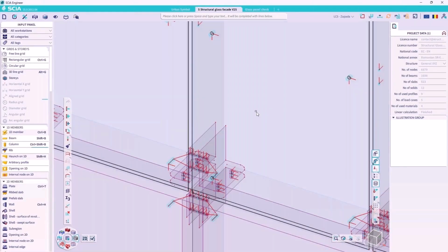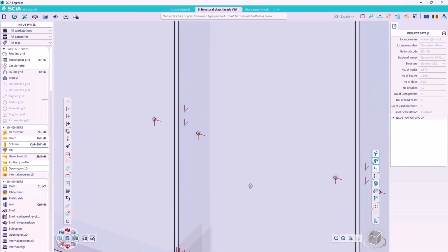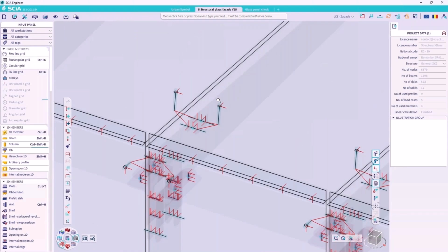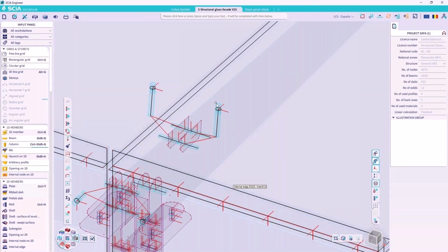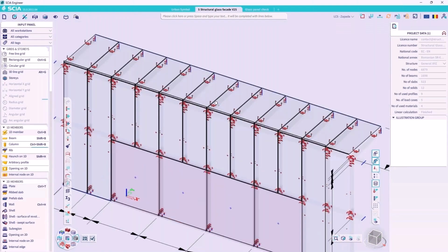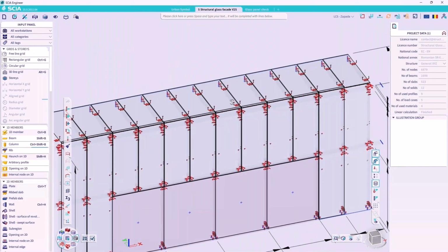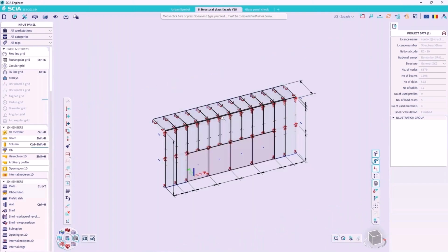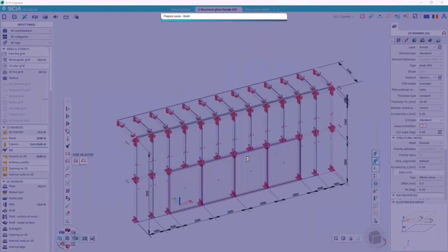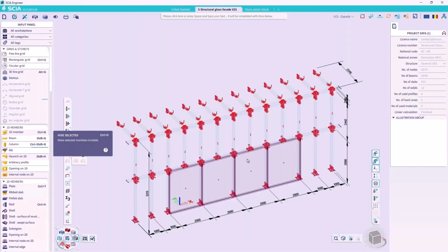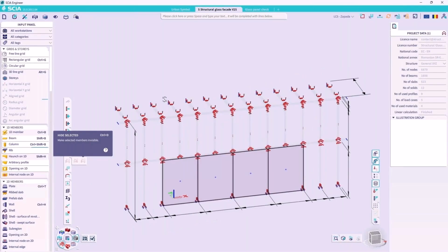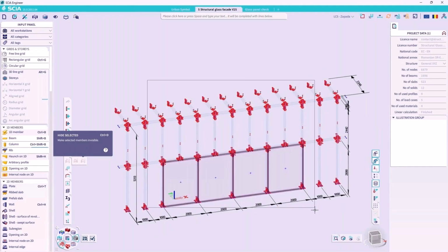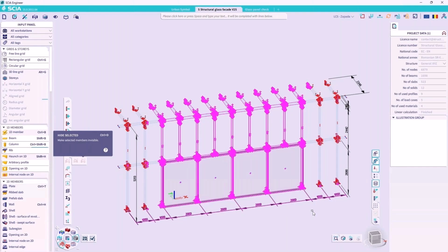And now we'll have a look at the star of the show, the structural glass element. We see that although the initial 3D model was done with 1D members, to check the capacity of the glass, the worst facade and the most stressed area identified in the 3D model can be checked using a shell model. So you see that each of the laminated glass elements is modeled as 2D shells with equivalent thicknesses depending on the laminated glass package. And these thicknesses are calculated by the software based on the user input.